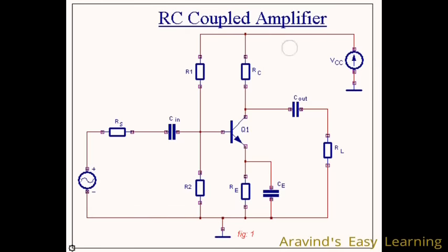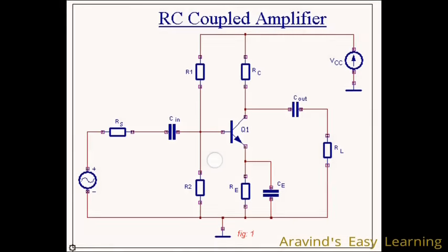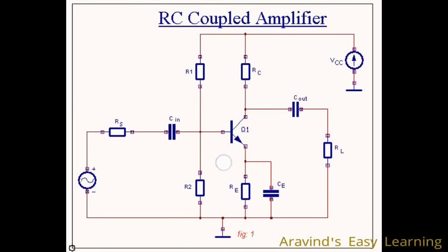You see, the VCC given is a constant, so if this drop is going to increase, this should decrease to keep VCC constant. So when the input base voltage VB is reduced, the output gain will also get affected and will not get proper amplification, and this unwanted drop in the resistor should be avoided.